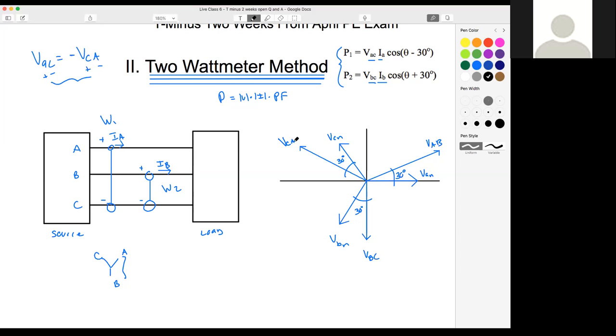So let's look at that. How do we go, right? Here's our C line voltage with our polarity from C to A. How do we go from VCA to negative VCA? I'm going to pick red for negative VCA. How do I draw negative VCA on my polarity? Heidi said multiply it by 1 at 180 degrees. So essentially we can rotate it either counterclockwise or clockwise. It doesn't matter. As long as we rotate it by 180 degrees, either direction is going to get us into the same spot.